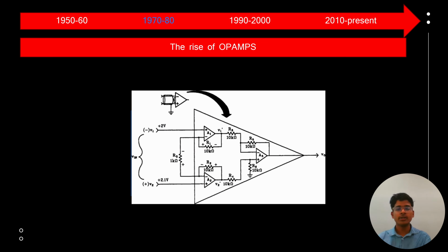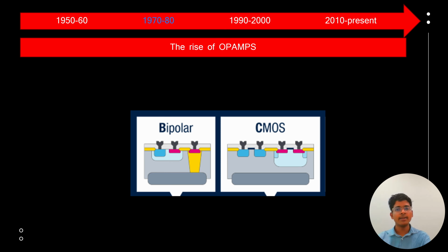As the IC technology matured, engineers started focusing on instrumentation amplifiers. Analog designers perfected the common mode rejection ratio, which we'll discuss in upcoming slides, to extract these tiny signals from our body. The 1980s saw the transition from bipolars to CMOS technology, which increased the battery life from months to years.